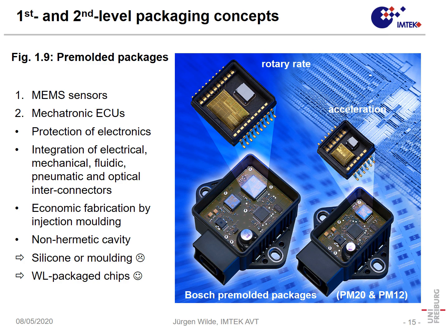Okay, such a device, again, when you produce MEMS, it is extremely hard to combine it with CMOS technology. In that case, we have a two-chip design in one package. That's a so-called first-level package. That's a package as we, for instance, solder it on a printed wiring board. So here we have the MEMS, and here we have the ASIC, application-specific integrated circuit.